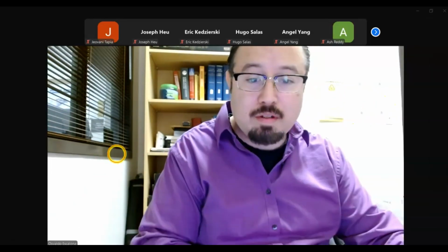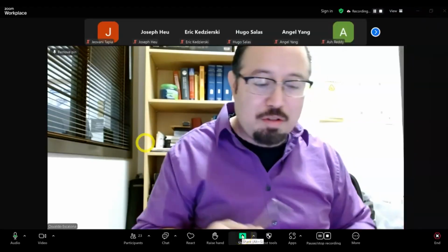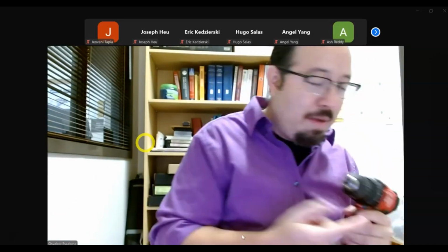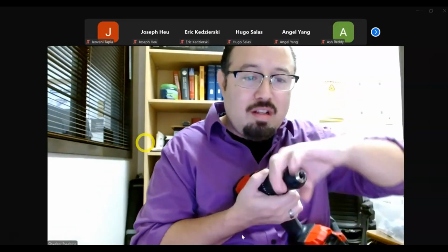Well, I'll show you. You guys will notice that your drill bit has certain areas that are flat, and that's where the chuck is meant to close and grasp it, right? You don't grasp on the flutes. If you grasp on the flutes, you're going to mess them up, and then your drill bit will not be good. The way you use a manual one, some people hold it and then twist it.